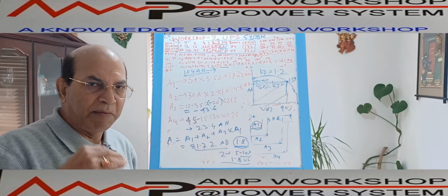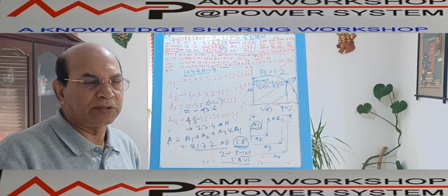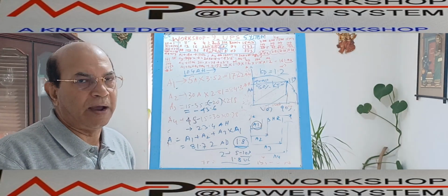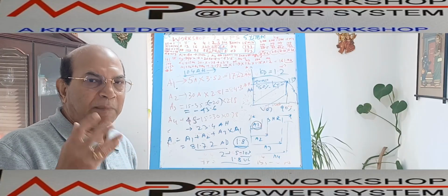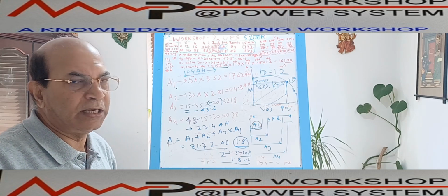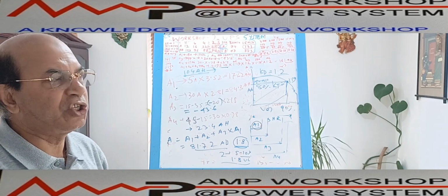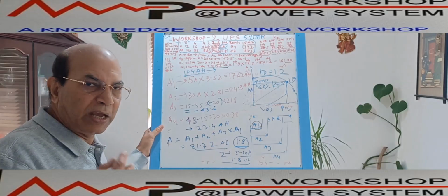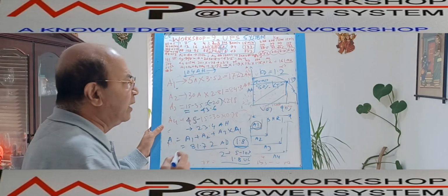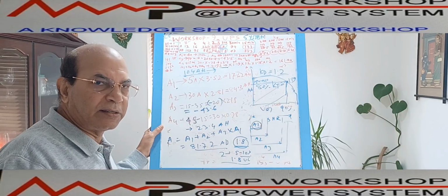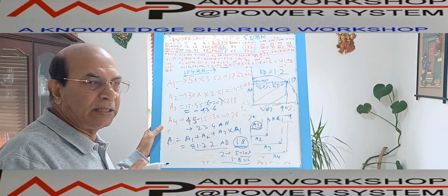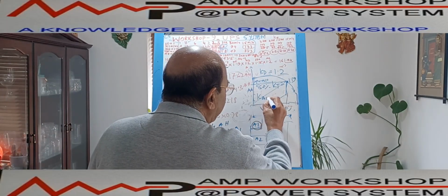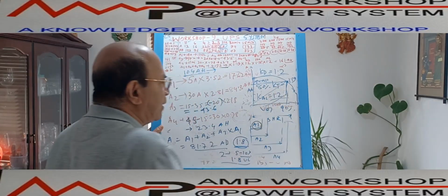So that's why every plant does the battery capacity test every 6 months, and they note how much capacity they have. That's why we need to consider a 20% capacity margin, considering the reduction of the discharge capacity. So there is another factor, aging. Due to aging, the battery has reduced its capacity, and we keep that 20% additional margin considering that capacity reduction due to aging. That factor, K aging, equals 1.2, because I have to keep a 20% margin for the aging.